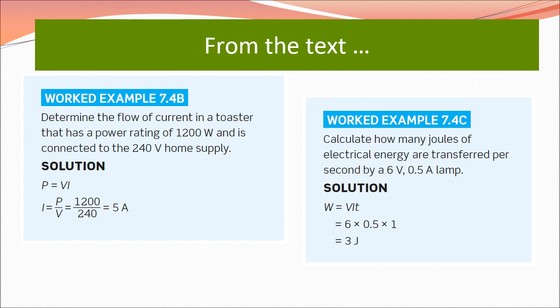Your home circuits are limited to how much current they can put out. So if you wanted to boil water in America using a 110 volt power supply, to get the same amount of energy transferred, the work done on the water, is going to take just over twice as long as it does in Australia using a 240 volt power supply. So that's a bit of trivia as to why most Americans don't use electrical kettles to heat their water.